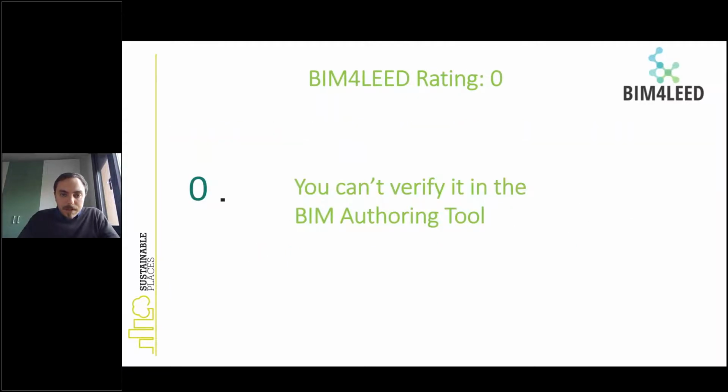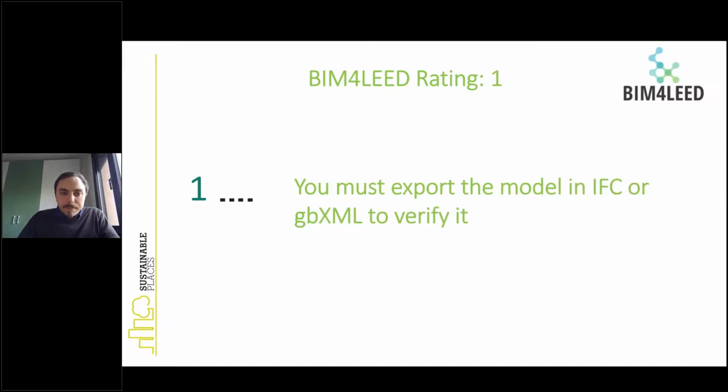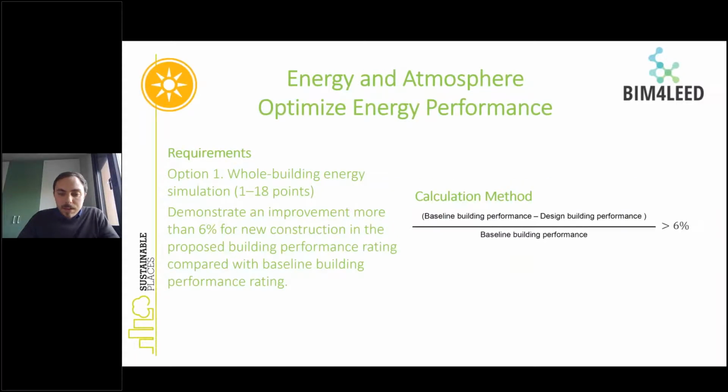So the BIM for LEED rating 0 is a LEED credit that is impossible to verify inside a BIM authoring tool. And the 1 is when you have to export in IFC or gbXML to verify it. It takes a long time and requires some experience and attention to do it. So we give only 1 point.